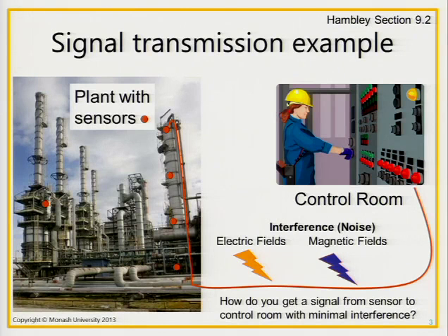So what we do now is we put sensors into those vats, or sensors wherever we want to monitor any particular quantity. Could be temperature, could be pressure, could be humidity, all of those kinds of things. In fact, a lot of those sensors you probably have on the phone that you've got right now. So sensors are really everywhere. And to do that, what we do is we connect those sensors back, usually through some wires, some long cables, back to a control room.